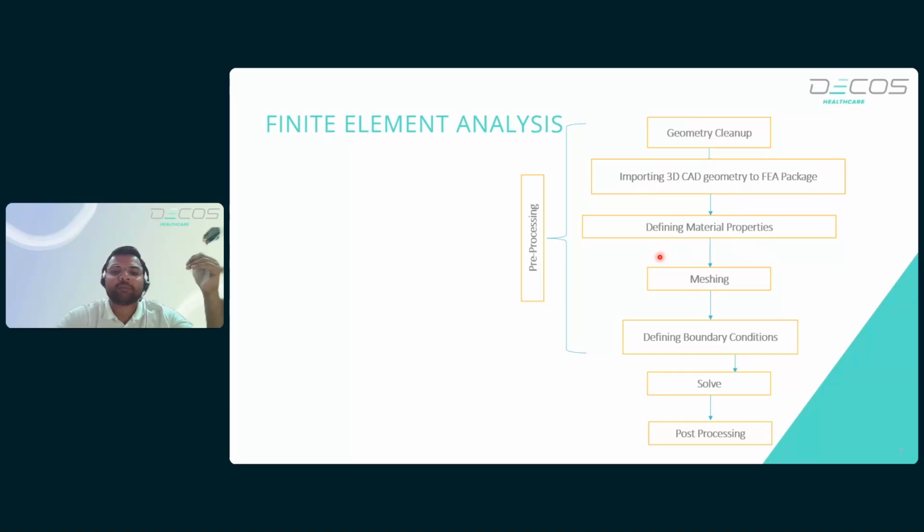Now, let's come to meshing, which is the most critical part of a finite element analysis. Meshing is the process of dividing the geometry into finite elements. Okay, and meshing is also defined as a process of dividing an infinite number of points into a finite number of elements and nodes. We'll discuss elements and nodes in my subsequent slide: what are elements, what are nodes, and what are the types of elements. Meshing is one of the most important steps to achieve accurate results. It is also called discretization. That's what we do. We create discrete elements of a complete geometry or complete model.